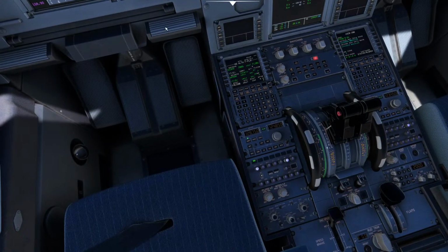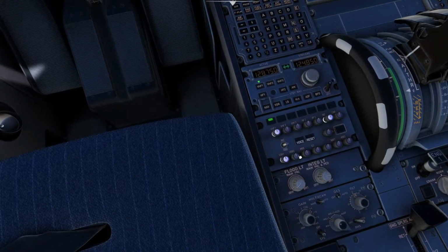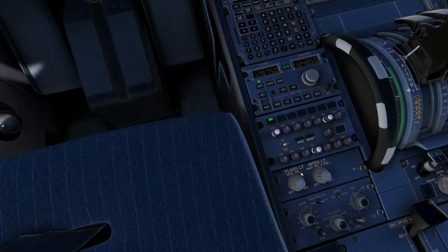but it will not ID the Morse. So you see how it says VOR1, VOR2, ILS? You actually have to pull it out to ID the Morse. It will auto-tune. It will tell you the ILS identifier, but obviously, technically, you're still supposed to ID the Morse, right? Like, that could be a check ride bust.